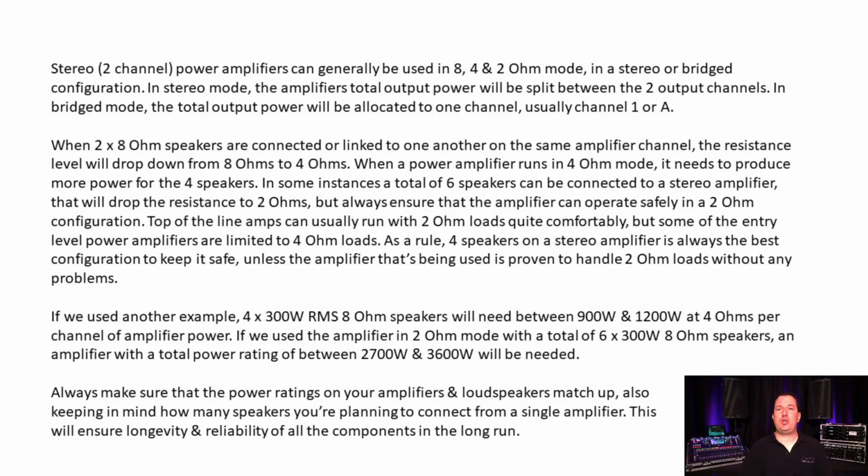Top-of-the-line amps can usually run with 2-ohm loads quite comfortably, but some of the entry-level power amplifiers are limited to 4-ohm loads. As a rule, 4 speakers on a stereo amplifier is always the best configuration to keep it safe, unless the amplifier that's being used is proven to handle 2-ohm loads without any problems.